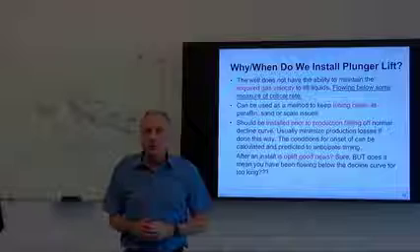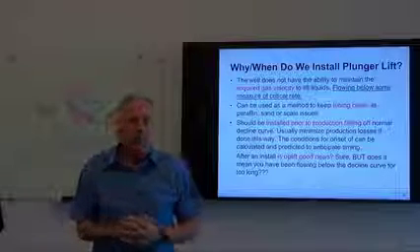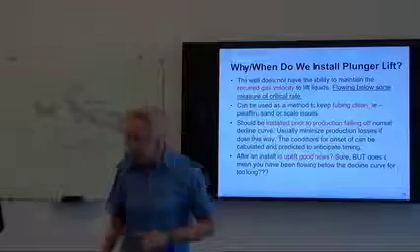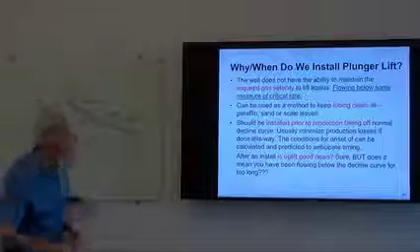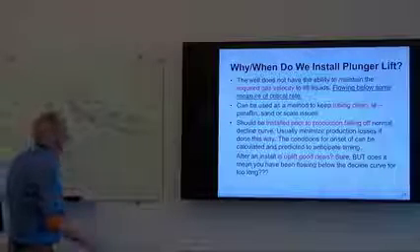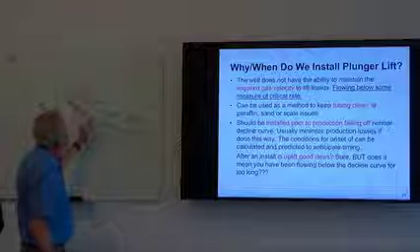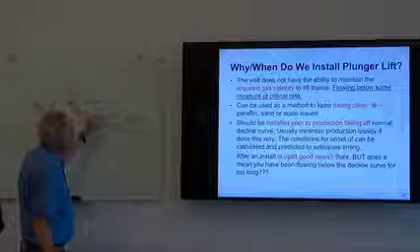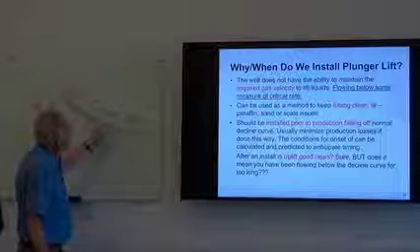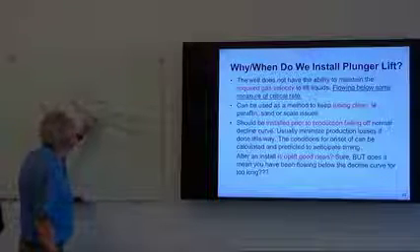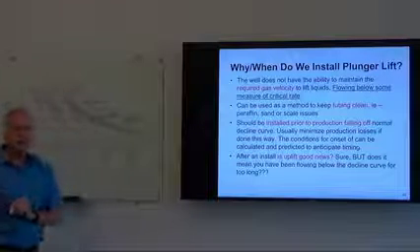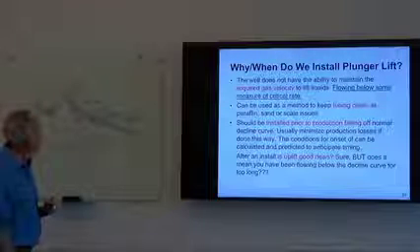After we install plunger lift, and let's say we see some uplift as good news, a good example right here again. What if I put in my plunger lift down here late in the life of the well, and I got a big bump in production? Eventually that production is going to stabilize at the natural decline of the well. And I might see a big bump up here for a little period of time, some flush production, for example.